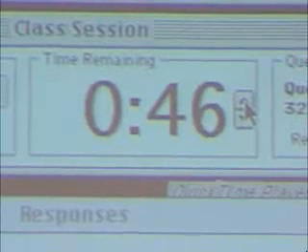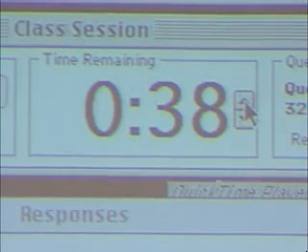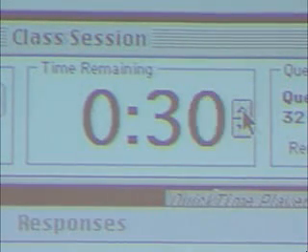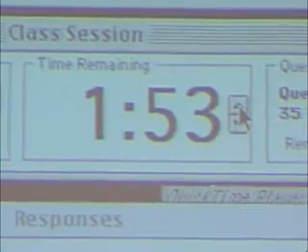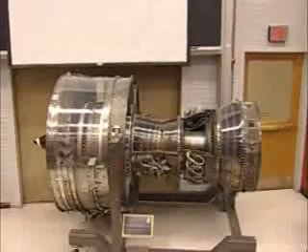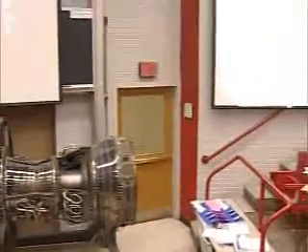Yeah, so this one, the flow coming in, is just coming in straight. So then what you want to do is say, well, the flow's leaving these blades at this angle. And then you want to subtract this to get into this blade's reference frame. So go all the way out to here, which is roughly what you did. Give us another minute or two at least, Carl. And then this is the relative one. And same thing, this is now the relative angle. It's the angle that comes off the blade. So you need to then get back to this. And then you want to look in this for what's the tangential component. It's really easier to draw right on top of those vectors like that.